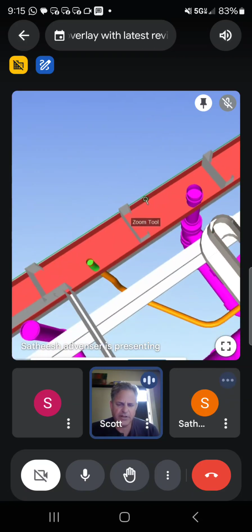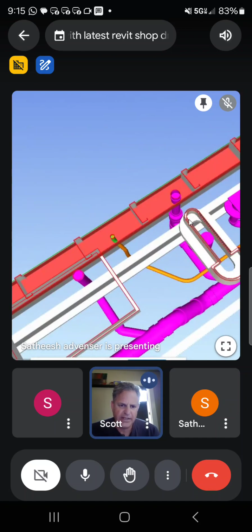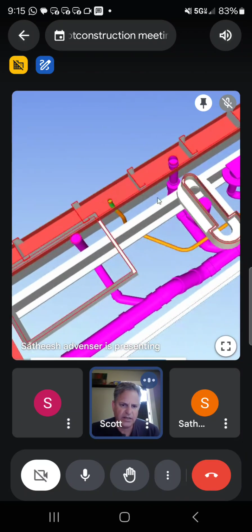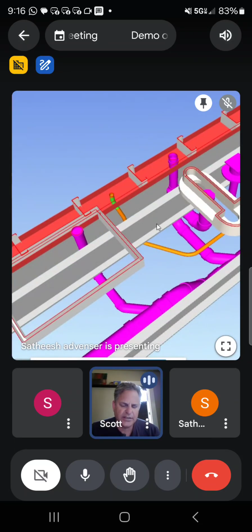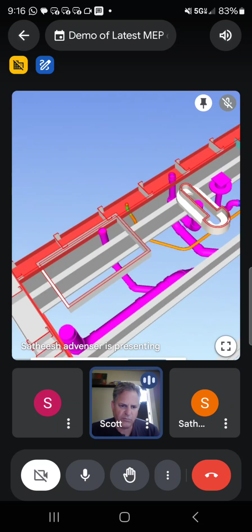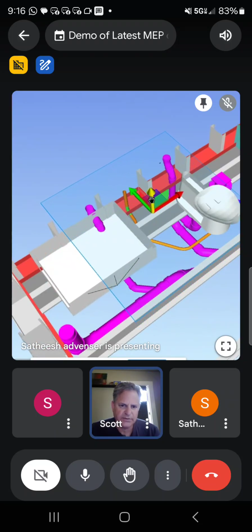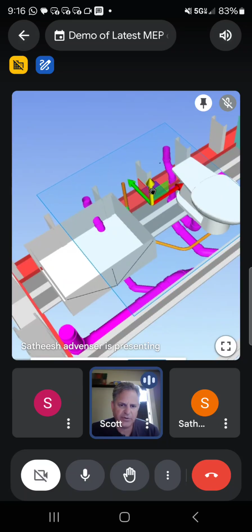We'll be able to actually punch a hole right in there for that. You have this so detailed that we'll be able to punch all the bottom plate, those holes right in there. That's where I was saying it's pretty critical to have all your penetrations that are coming up visualized on a floor plan for now, and then we'll modify and get back with you as we're building that wall. You know what I mean? As we're coming up through,